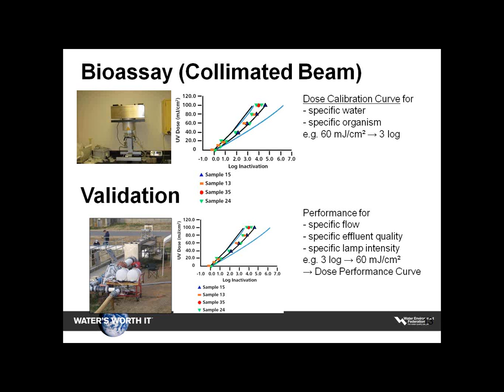Within a certain operating envelope, that equation is where it's been tested, and therefore where it's valid. So equipment goes through validation. Generally, the equipment manufacturers perform that service to come up with the equation that is then used to size the full-scale UV system, and then you match that up with your bioassay data